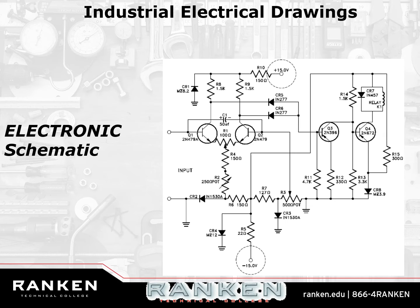Okay. And you go back to the side where the PLC cabinet is, you open up the door, and there's one I/O board, one I/O rack, and just completely black. No lights on, no nothing. Well, that can't be right. So you just pop that one out and pop a new one in. You go back over, you look at the PLC, the ladder, everything's green now. Hey, cool. I fixed it.